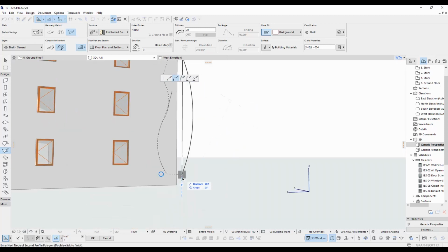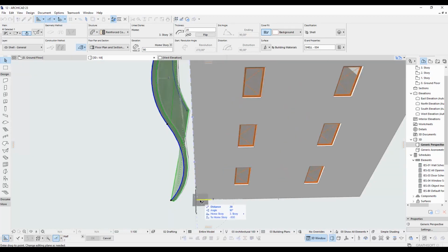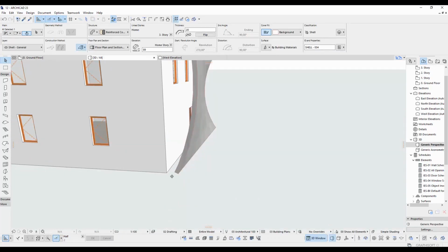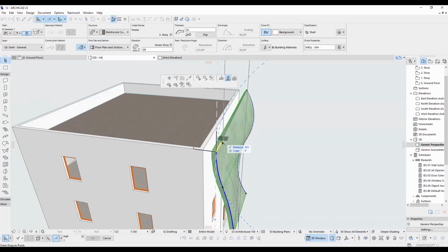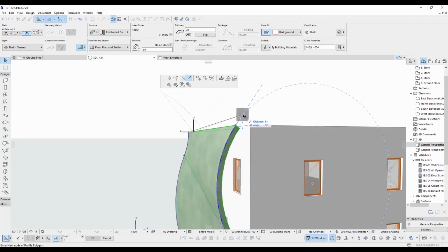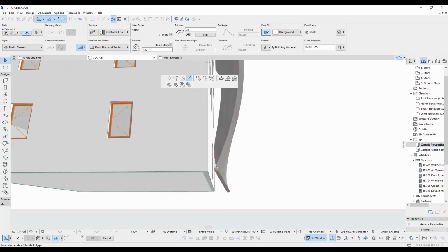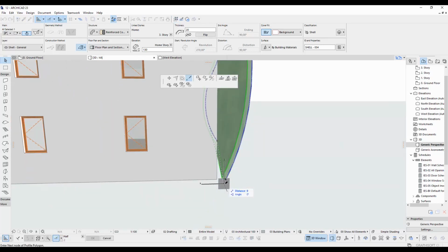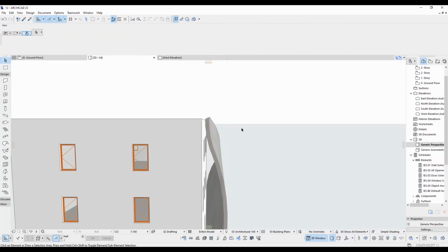I continue the design of the facade. I make sure that the joints of the face are smooth. After that, I will lengthen the ends and cut the ends. At the same time, I bring it closer to the building so that it is not too far from the building, and reduce the curves accordingly. I will cut the edges after I expand. I click the pen tool to do that, after selecting the blue line.